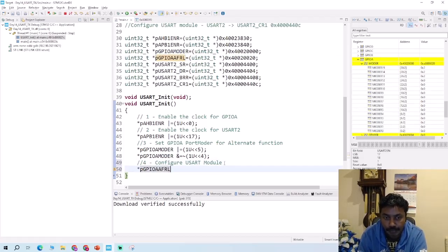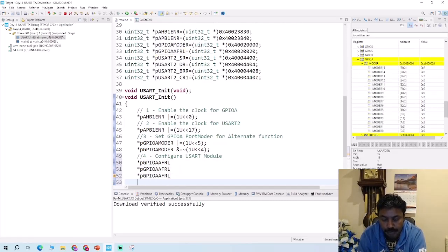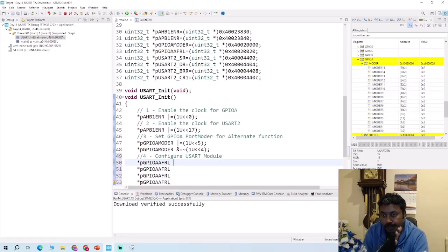So that has 4 bits. You need to copy 4 times. Control V, yeah. And then you can start the same way as you see in the register, 11, 10, 9, 8, or you can go the other way, 8, 9, 10, 11. It's up to you. Either way you can program, but the main part is if you want to negate, you have to negate that bit. If you don't want to negate, just leave it as R. So I'm going by how you see the register. I'll show you how you see the register.